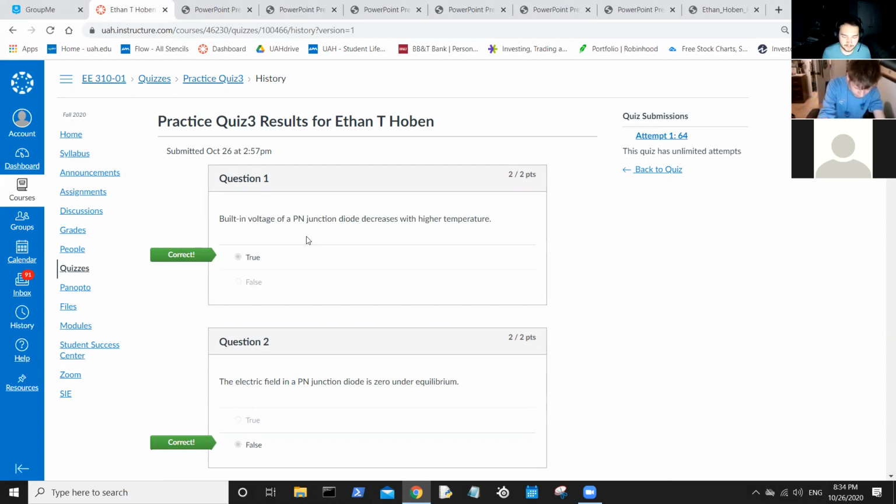Now, if you look at only that and don't consider any other external potential factors, you see that T is in the numerator of that fraction. That, of course, is your temperature in Kelvin. If that temperature goes up, you would expect the voltage to go up, right? Because it looks like it's just a linear relationship. But as we see, the correct answer is it goes down. It's not a linear relationship.